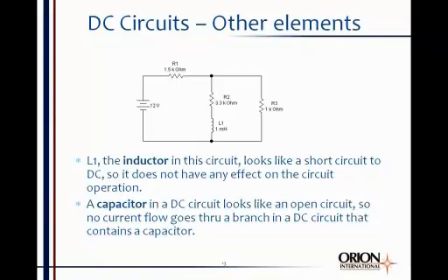All right? And capacitors look like open circuits so that no current flows through any branch in a DC circuit that contains a capacitor. Those are handy little tidbits of information to know. Inductors look like short circuits to DC. Capacitors look like open circuits to DC.